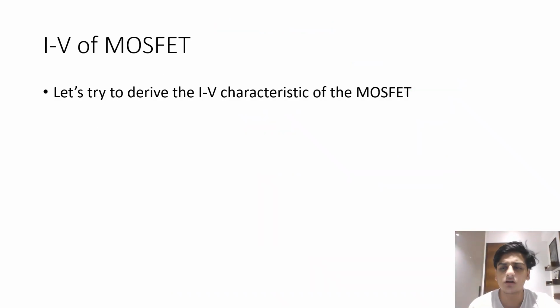I hope it's now clear how, in principle, a MOSFET works, where you have this band bending. When it happens beyond the extent by increasing the gate voltage, an inversion layer gets formed. That inversion layer can become, if you continue increasing the gate voltage, very strongly n-type, which means it can conduct very easily.